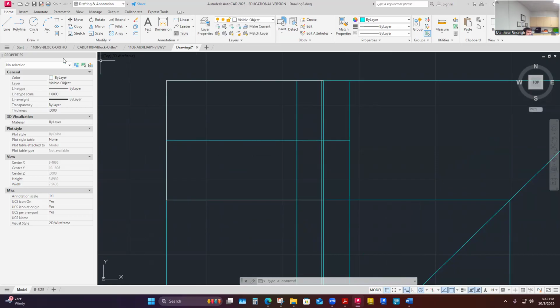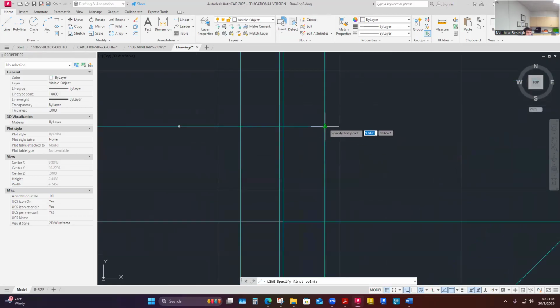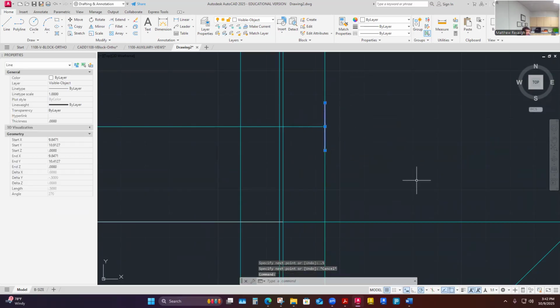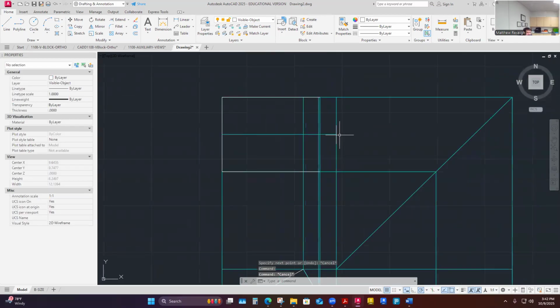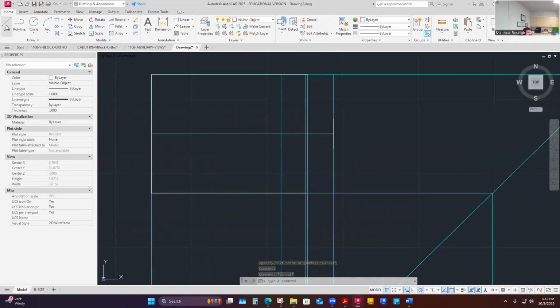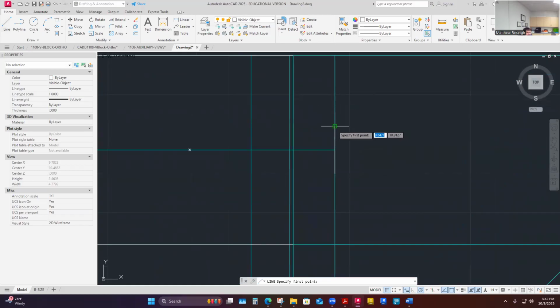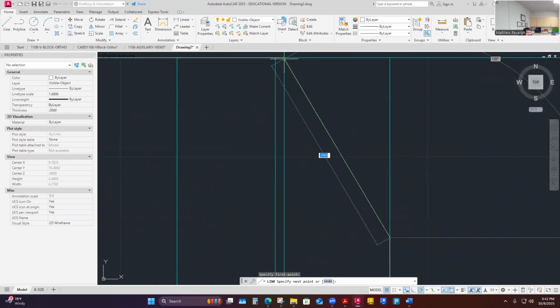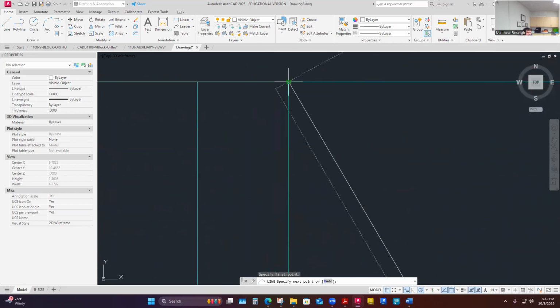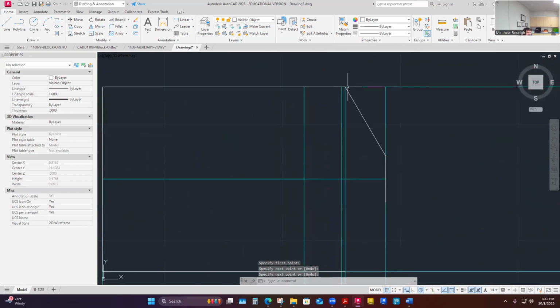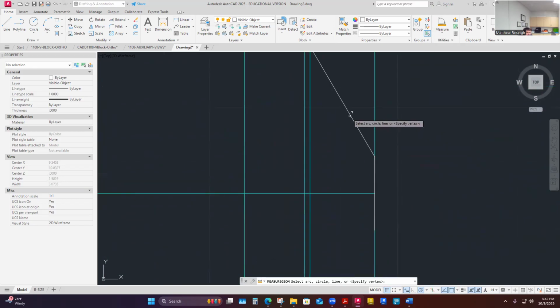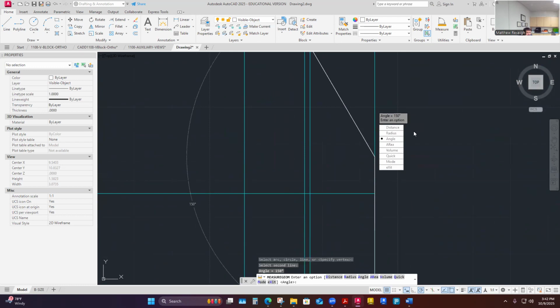I'm going to go back to my visible line. Just to be really sure, maybe I'm going to cursor over here by 0.25, and then I'm going to draw a half-inch line. So it looks like that. That's a half-inch line. That's what I would see on the right side surface. And then from there to there, I really don't even need the degrees because I just have that from here to here should be, and I'm going to zoom way in here, make sure I'm catching the right point. Enter, yes. That should be 30 degrees, right? And I'll just do a quick measurement, but we can see that these can be inaccurate, so I have to be careful. It's a good check.